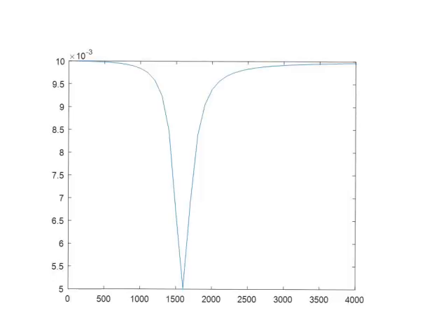If you plot it, and this plot is coming from MATLAB, this is what you're going to get. Again, the resonance frequency is the same one we had earlier, maybe about 1600 hertz or so. At that specific frequency, the impedance seen by the source peaks, and as a result the current reaches a minimum. The current is going to drop. Notice here, why does the current drop only to 5 milliamps from its maximum of 10 milliamps?